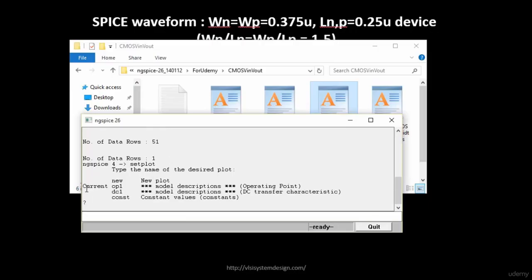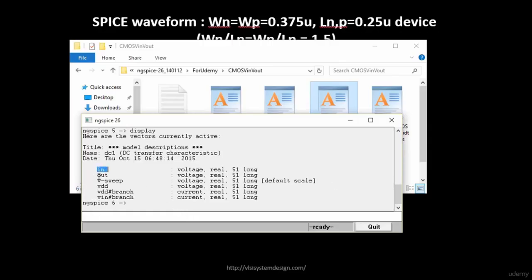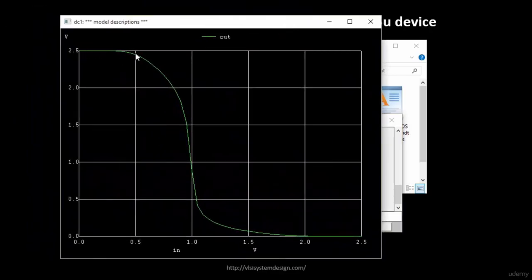We'll start with the model file. So let me show you the model file first. Okay, so this is your model file. This is where it has got all the description. You have the model NMOS, its name is NMOS, and these are all the technological parameters with respect to this particular NMOS. Similarly, we'll have something like PMOS also. So this is the dot model, the syntax of describing the PMOS technological parameters. You have this PMOS, which is the transistor name, and this is the complete description of your PMOS transistor. So it will have all of the parameters that we described in our past videos.